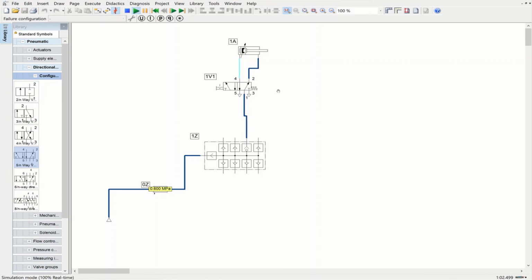Okay, we are done with this session. We covered the information related to directional control valves, how we name them, the differences between the different forms of directional control valves, and how they can help us within a pneumatic circuit.